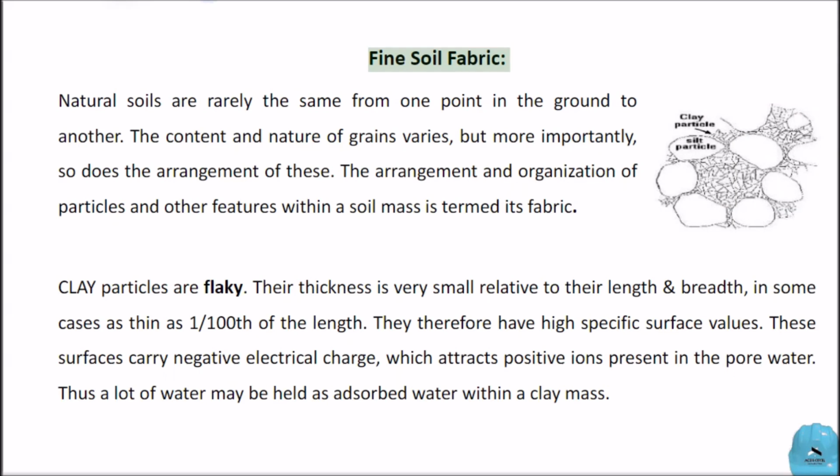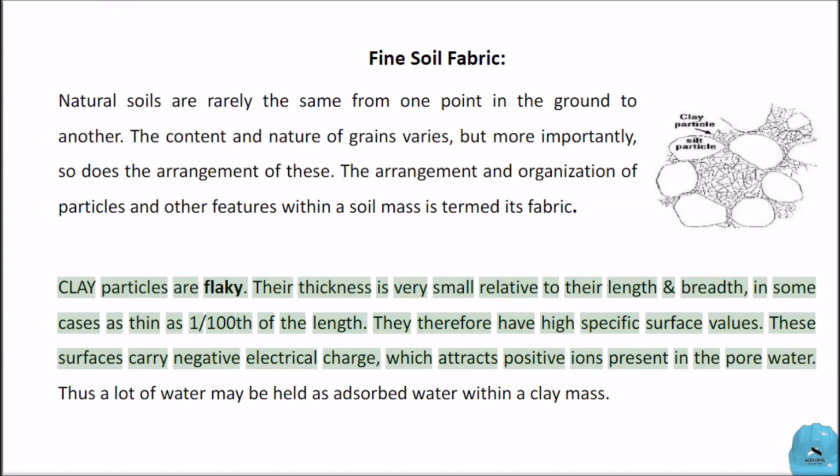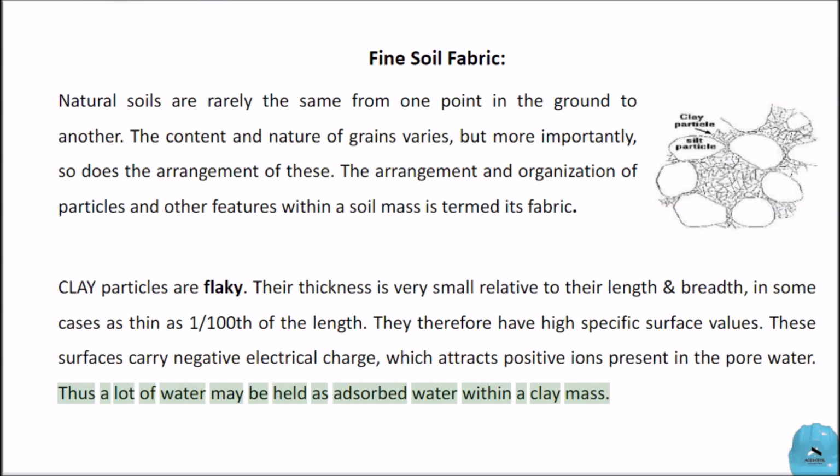Fine soil fabric. Clay particles are flaky. Their thickness is very small relative to their length and breadth, in some cases as thin as 1/100th of the length. They therefore have high specific surface values. These surfaces carry negative electrical charge, which attracts positive ions present in the pore water. Thus a lot of water may be held as adsorbed water within a clay mass.